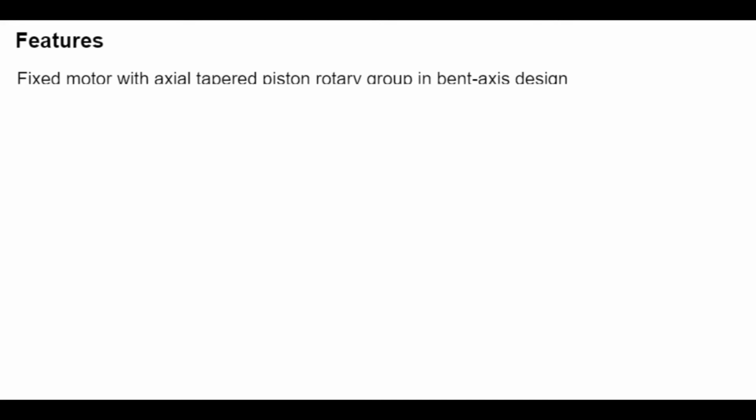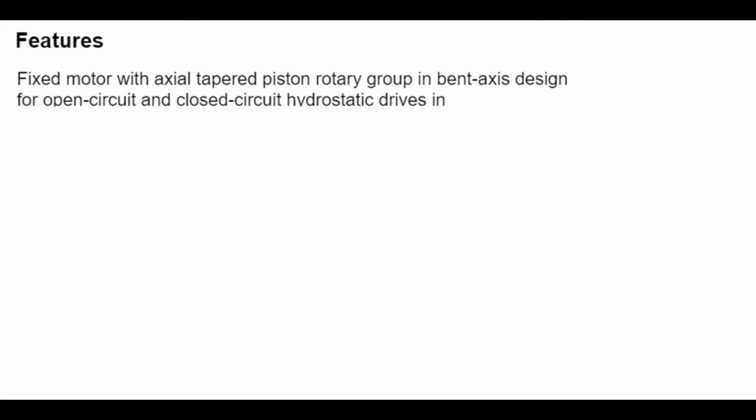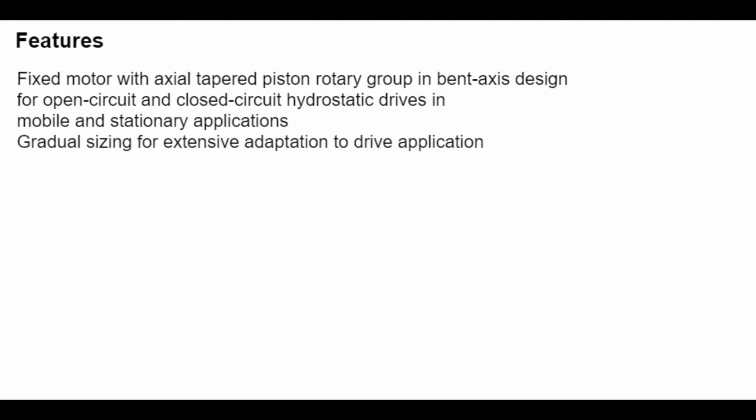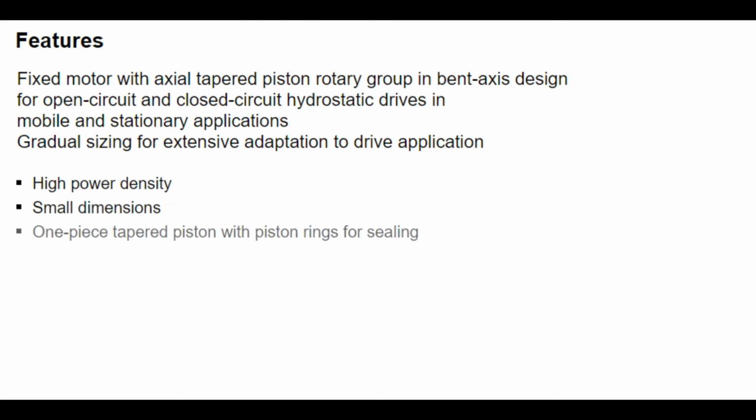The Rexroth A2FM and A2FE fixed motor with axial tapered piston rotary group is used in open-circuit and closed-circuit hydrostatic drives for mobile and stationary applications. The gradual sizing offers extensive adaptation to each drive application. The large angle unit with a 40-degree swivel angle has high power density and small dimensions. The one-piece tapered pistons with piston rings produce good starting efficiency and high overall efficiency.